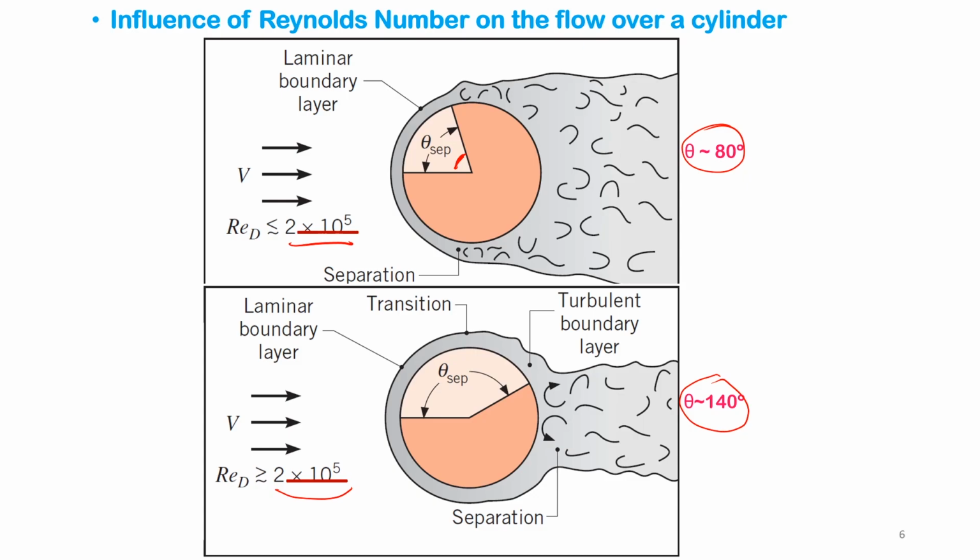Just think about a viscous material where you are trying to increase velocity. Reynolds number is directly proportional to velocity. Let's say in the top case we have a small velocity. That means the fluid is not going to be forced to conform and grab on the cylinder, so it is only going to conform to the geometry on the front part.